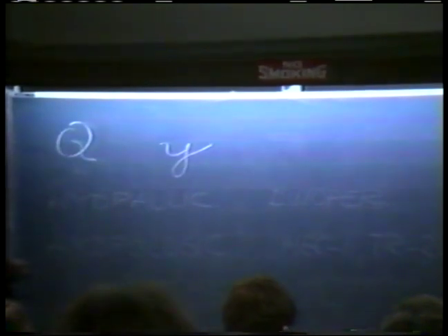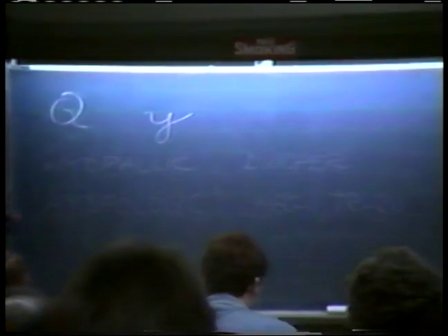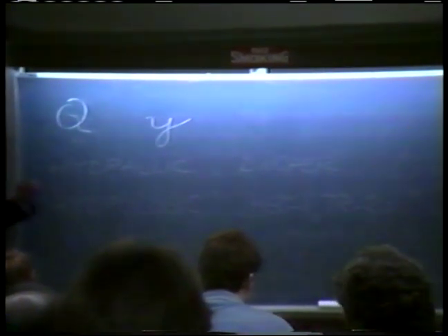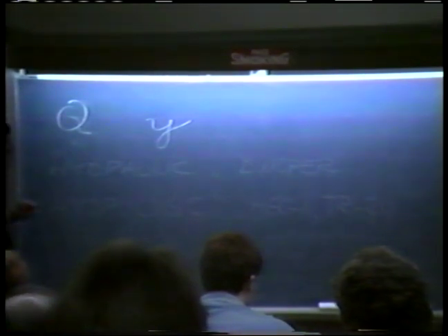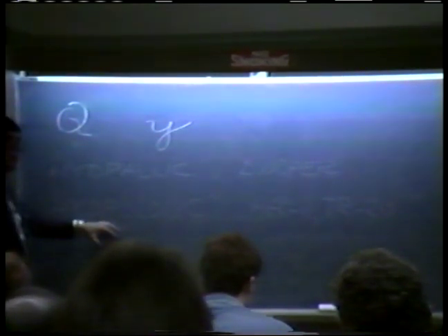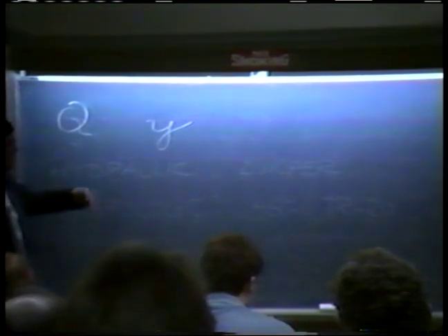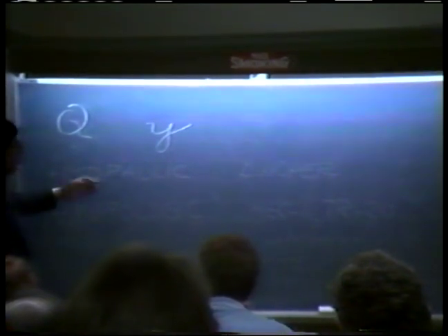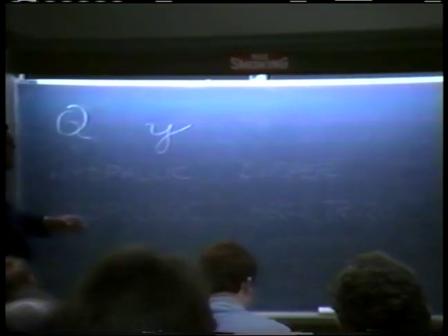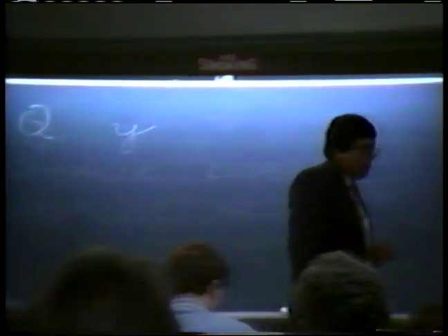So the main thrust of our analysis here, as well as this afternoon, would be to determine what is the difference between these two approaches. When can we afford to go the hydrologic way? And when are we getting out of the limits in which we could do this calculation in a hydrologic fashion, and we have to go perhaps to a more elaborate model that will give us simultaneous calculation of discharge and stage?